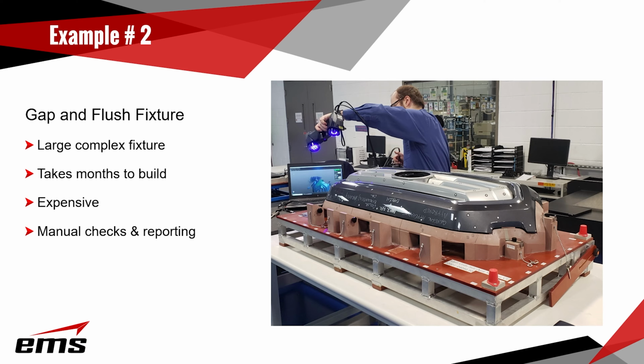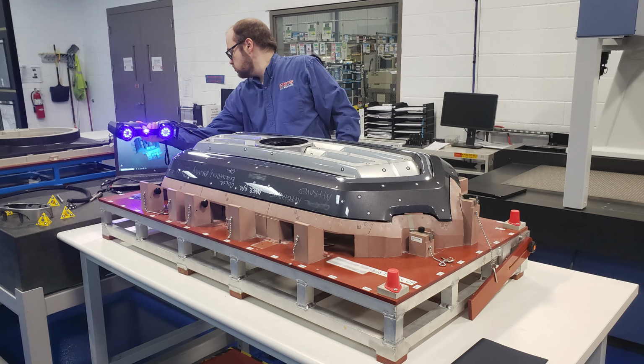So you place the part on this fixture, and then there are these little chains or pins that you slide in there to measure that gap. So you see that gap on that panel. You want that to be consistent all the way around. So if that pin doesn't fit in, the gap would be too small, and if there was play or slop in there, it would be too big.